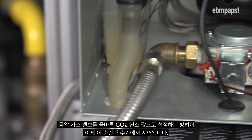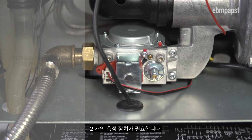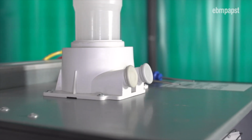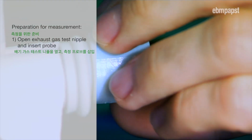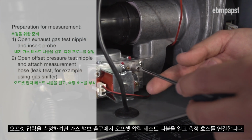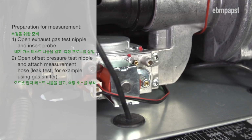How to set a pneumatic gas valve to the correct CO2 combustion values will now be demonstrated on this instantaneous water heater. Two measuring devices are required: a pressure gauge for pressure measurement and an exhaust gas measuring instrument for measuring the CO2. To perform the exhaust gas measurement, open the exhaust gas test nipple and insert the probe in the exhaust pipe. To measure the offset pressure, open the offset pressure test nipple at the outlet of the gas valve and attach a measurement hose.